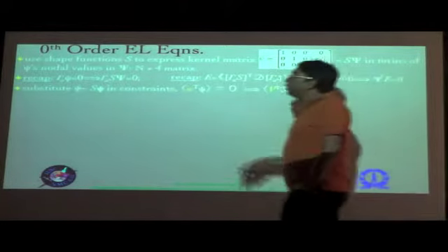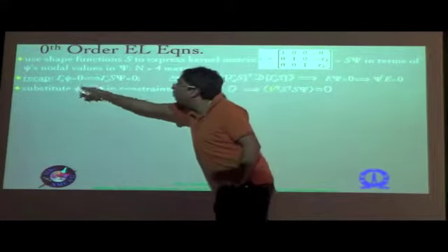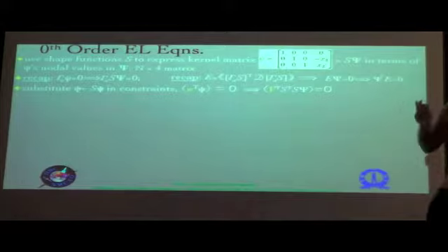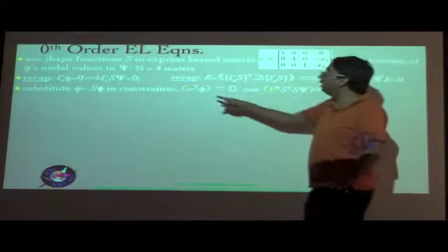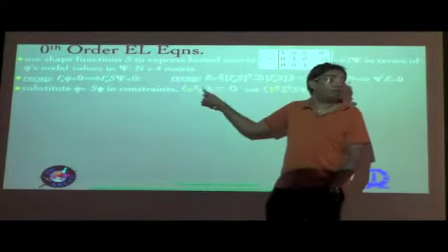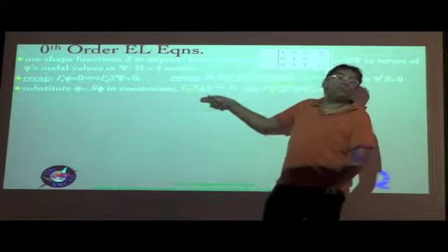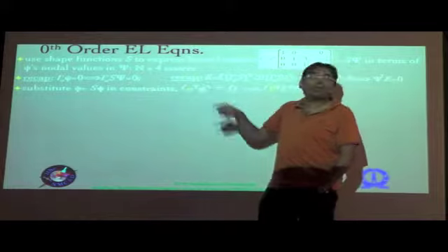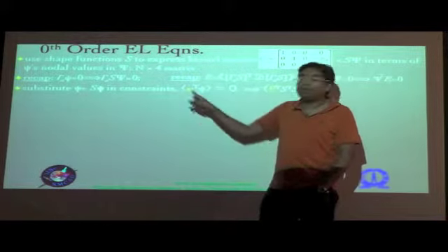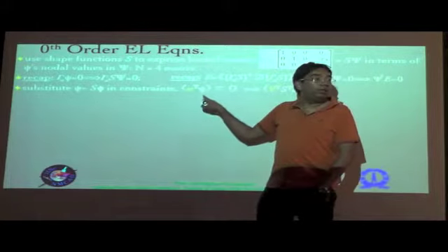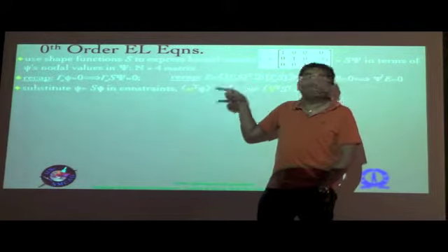Now we substitute this discretized form of the kernel matrix into the constraints itself. The constraints, remember, were such that the warping should be orthogonal to the solutions which is indicated by the kernel matrix, and therefore W transpose times I integrated over the cross section equals 0. And here note that it's not a double angular bracket, so no root g is involved here.